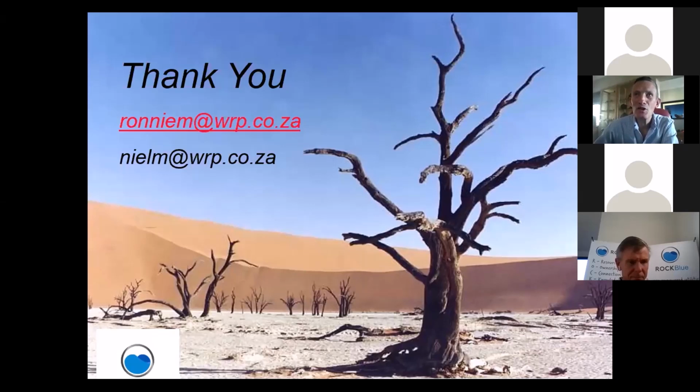It's a really good question, that one, and not one I can really answer within a couple of minutes. Generally, if you have a city or a whole area, you would normally try to carve up the area from the outside, moving towards the middle, so that you're looking to isolate an area that you can cut off with just 1 or 2 pipe cuts, and you shouldn't have to have 20.